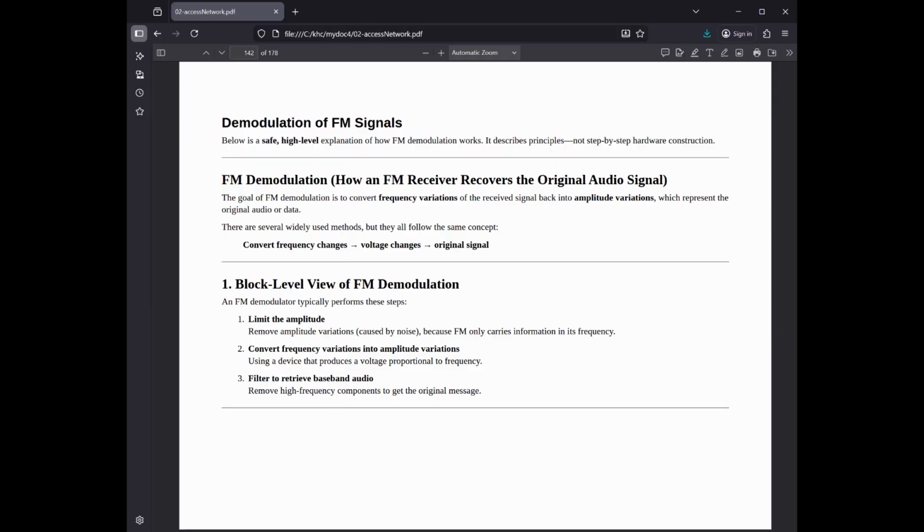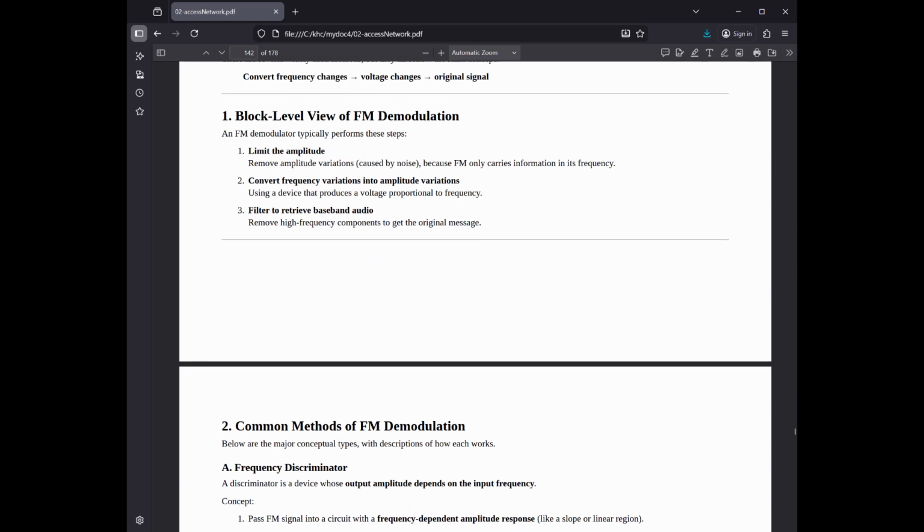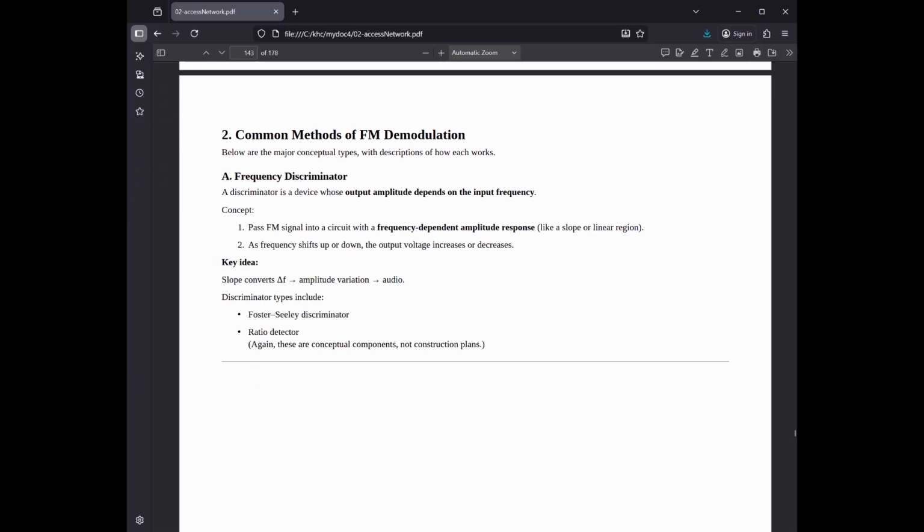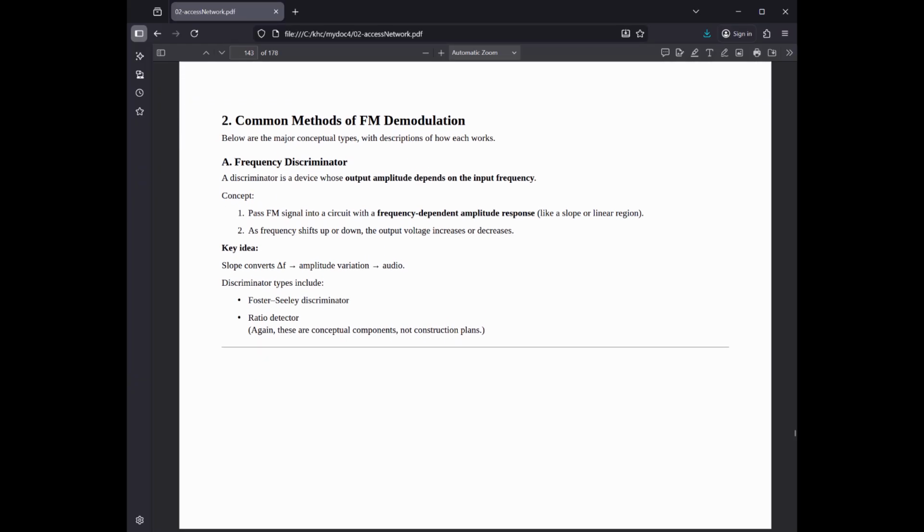1. The core requirement: frequency-to-voltage conversion. An FM demodulator must produce an output voltage that changes in sync with the input frequency. To do this effectively, the circuit must follow 3 rules. 1. Linearity: the voltage change must perfectly match the frequency shift to avoid distortion. 2. Noise rejection: it should ignore changes in amplitude, static and noise. 3. Sensitivity: it must detect even tiny shifts in frequency.